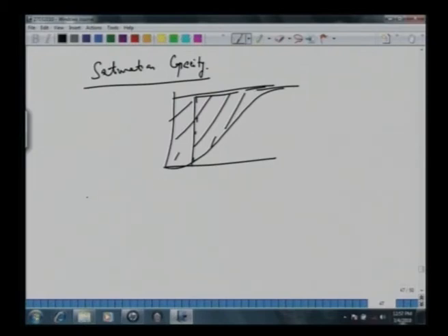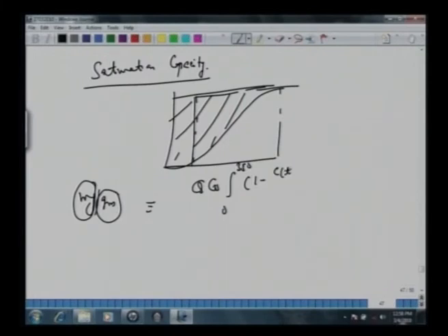So saturation capacity is nothing but milligram per gram. How many milligrams of adsorbent VOC has been adsorbed per amount of this adsorbent. So how much it has been adsorbed, you have to integrate Q C0, 350 minutes, that's your saturation time, 1 minus Ct over C0 into dt.